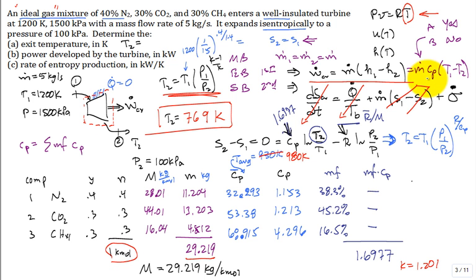That's the correct approximation. We had the specific heat of the mixture. We had the two temperatures. You calculate the m dot. I'm going to erase right here, not the m dot. You calculate the power. W dot is equal to, and you get that the power is equal to 3730 kilowatts, good to 3 significant digits.